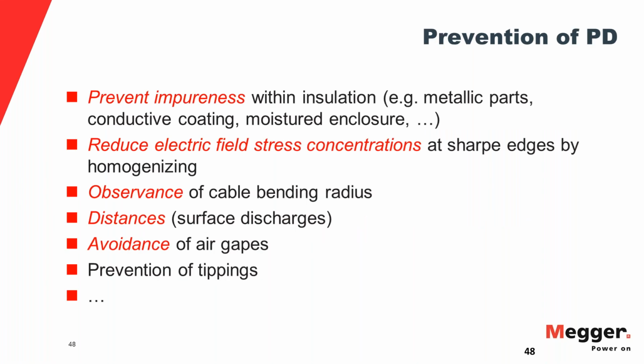So how do you prevent this? Well, you do a good job, actually, and you make sure that your splicers are educated very well on the different splicing technologies. See, there's a saying in Europe, specifically in Germany, the wealth of the utilities is underground. Because if you do the installation properly and you have a very good cable from the beginning and the jacket is undamaged, so you did your sheath fault testing as well, then you have a printing press, kind of, because the asset is there, minimum maintenance, especially on the latest generation tree retardant XLPE in terms of water treeing.